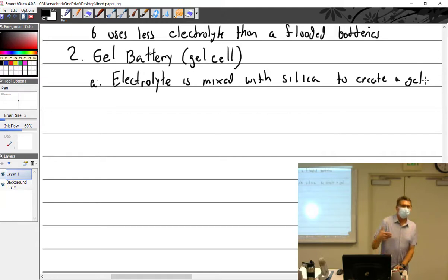Anyway, the reason I'm asking what it is, is that as an aircraft mechanic, silica comes up all the time on oil analysis. If you have an oil analysis done, which a lot of people do, and you have a high silica content, you need to know what silica is and where it comes from. It's a little different in this case, but it would be funny if it was the same thing. What is sand?